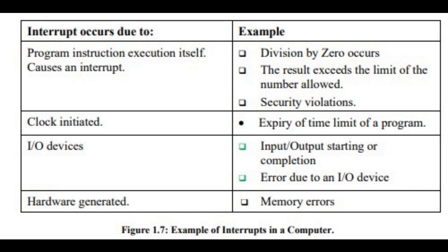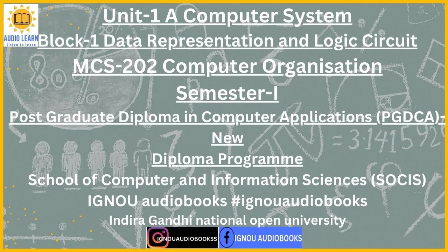The CPU executes an interrupt servicing routine, ISR, which services the event that has occurred. Meanwhile, the program which was being executed is moved to a hold state. Once the CPU completes the ISR, i.e., executes it till its completion, it resumes the execution of the program it has put on hold.